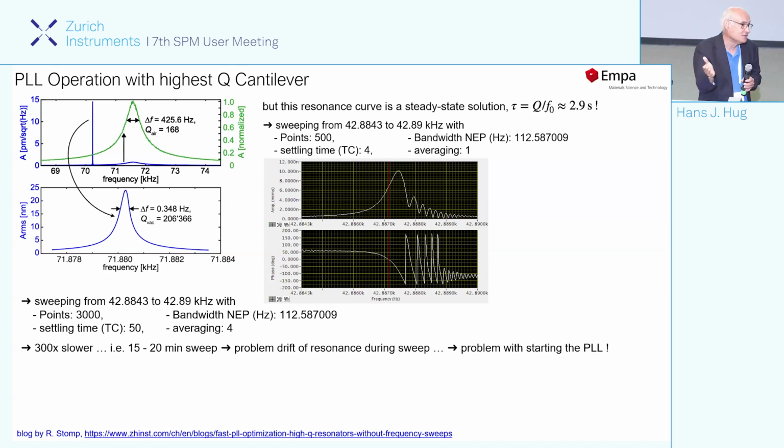So how we find it is usually by a thermal noise analysis. And then we do a local sweep. We don't care about the beating. We may do a slow sweep knowing that this is not correct, close the PLL somewhere, and then do this phase sweeping as introduced by you. So that works very well.